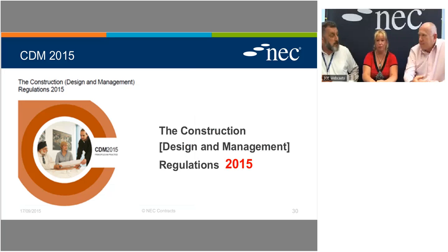Notably, there's now more duties on the client. They take more responsibility, which is right, because under contract, the client starts it, the client initiates the design, the client initiates construction. They choose what they want and how it's delivered. So they should have some responsibility. Another major change is the CDM coordinator role has been dispensed with, and now there's a principal designer role, which means that one of the designers has to take the lead in making sure that all the design components fit together. It's a complete design. That's a step right up there.